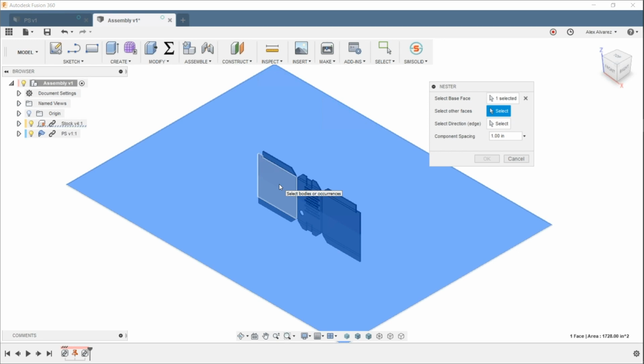What you can do actually, instead of creating some sort of flat pattern, is unfold the sheet metal components that you had. As long as you have them in the same orientation or you just have them inside of that previous drawing or model file, you can bring multiple files into a single sheet size. I remember doing a sheet metal webinar where I was using a flat pattern, and then I activated the flat pattern, and then I created some sort of CAM toolpath based off of that.